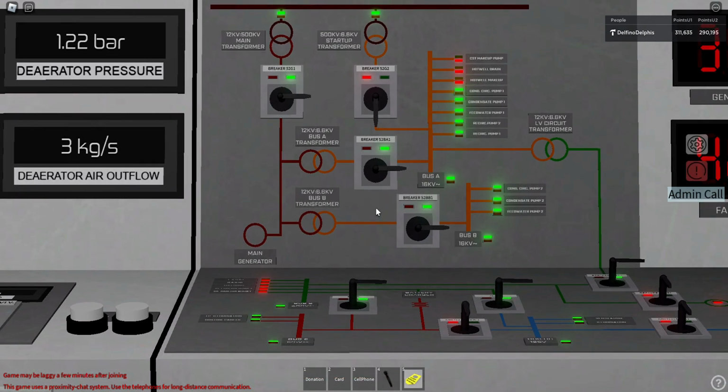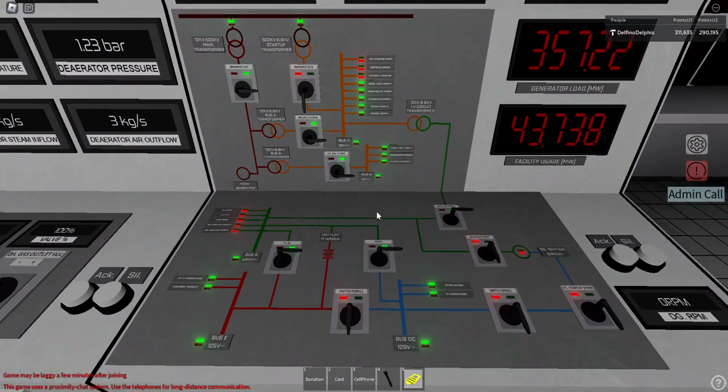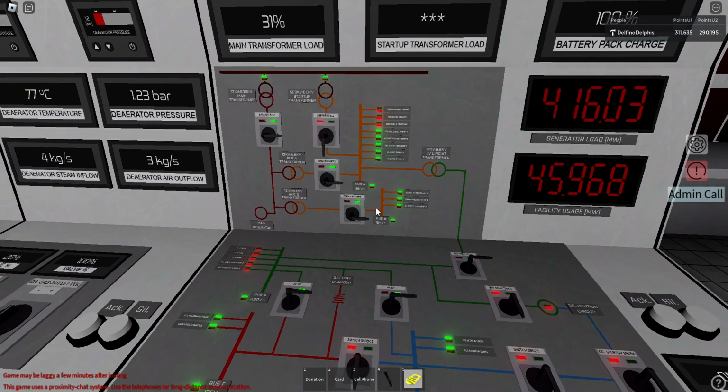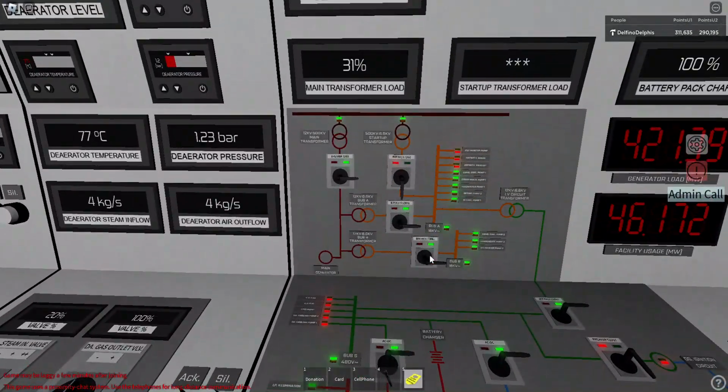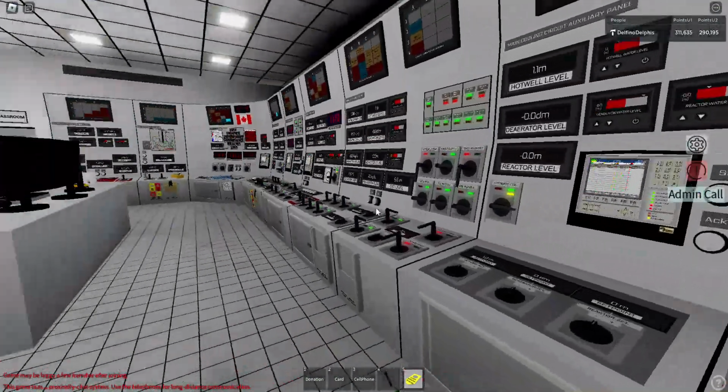Basically, all gets dark. So the first thing you want to do is to power your DC bus, so the lights and the ventilation, from the emergency bus. This is the first thing you do, because then you get the lights back at least. And once you have lights back, you have no power to any of this, so you don't have any pumps, and the water is still boiling in the reactor.